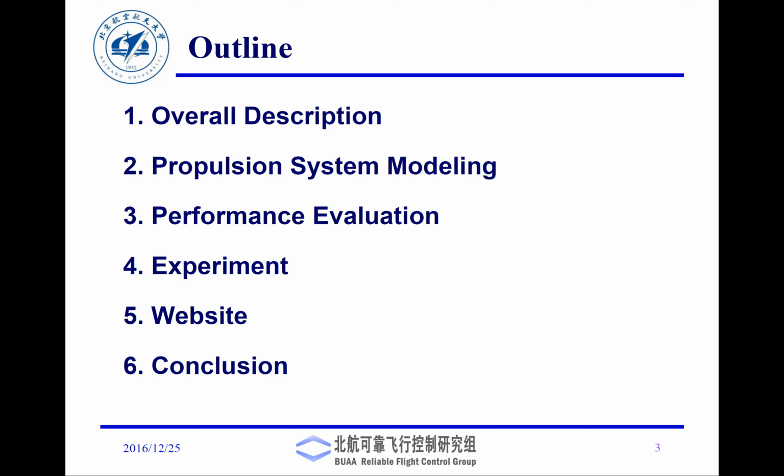Then if you have some additional requirements, like you want that UAV to loiter for a certain duration of time, say operation time is like 20 minutes, you make sure that the system that you have selected is capable of supporting that much amount of power. And you go through these different test cases and finally come up with a final design.